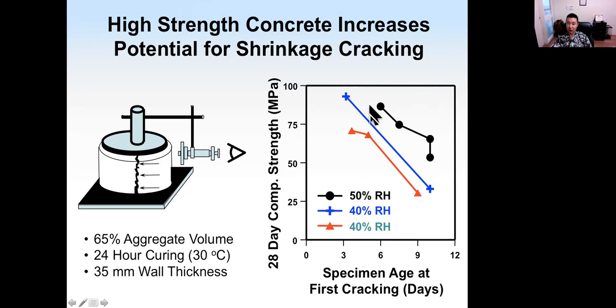The concrete will experience a different percentage of RH, which is relative humidity. So at lower relative humidity, the concrete will crack early, for the same type of stress level.